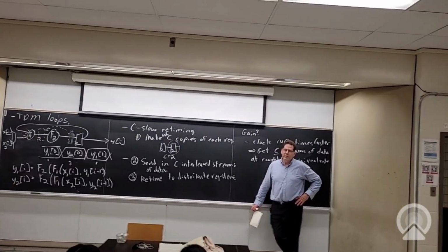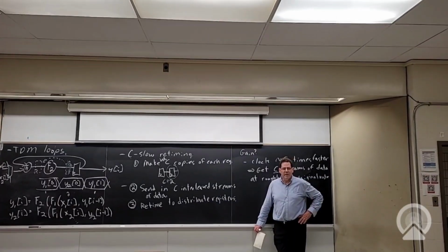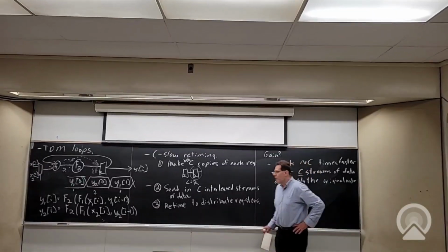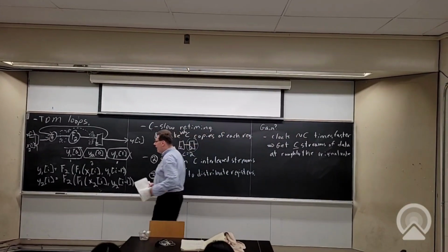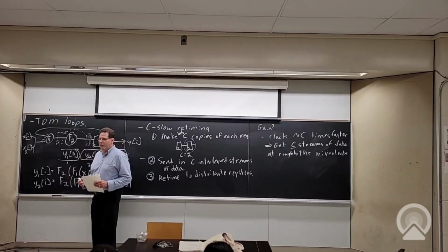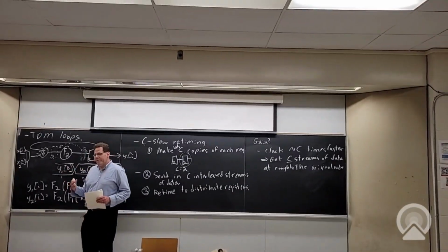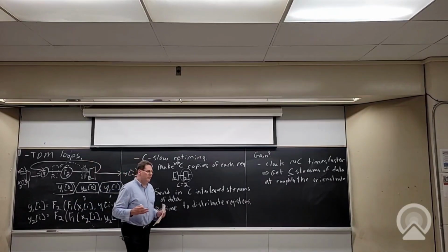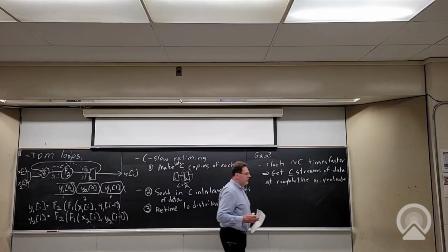So in theory, you go, couldn't a CAD tool do better than a human? And in some ways it can. It knows the delays a lot better than you do. So if you look at Quartus, if you actually watch the output of its compiler, you'll see that it does retiming in multiple spots. So it does some retiming in synthesis.